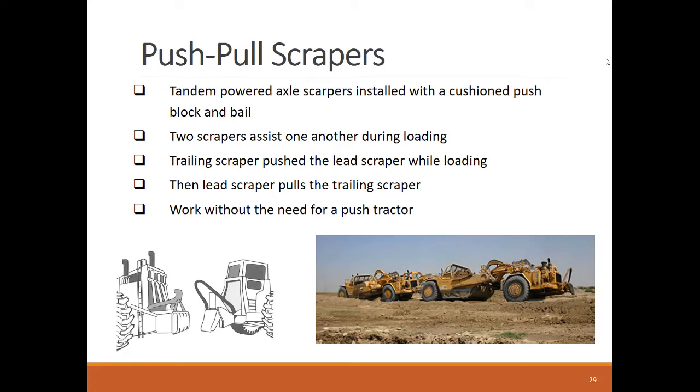Push-pull scraper operation is also a two-link system in which two scrapers help each other in loading. This is done through block and bail to allow two scrapers to safely connect together and help each other in cutting and loading the soil.